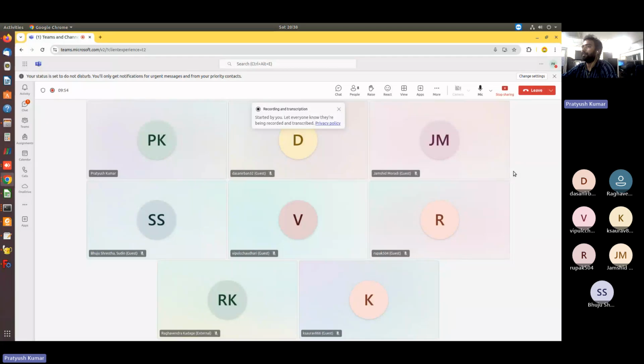If you know how to access ParaView Python scripting, then you can optimize your post-processing. Sometimes you want to do post-processing, and if you have some idea about how to write Python code in ParaView, then you can do repetitive tasks using that script only, and it's not very difficult.